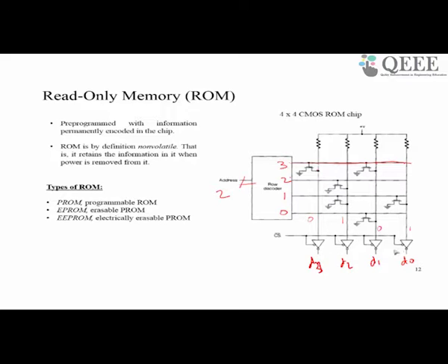So we can read out of it. Here we have a group of active low buffers. When the chip select bar is enabled, these tri-state buffers are selected, and we have a bubble here, so whatever the content is, it is negated and given here. So effectively we will have a value 1010 being read out.